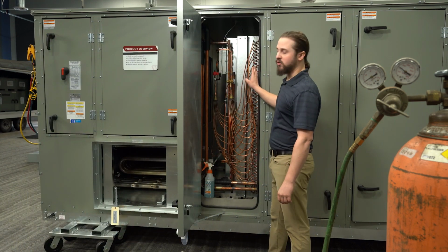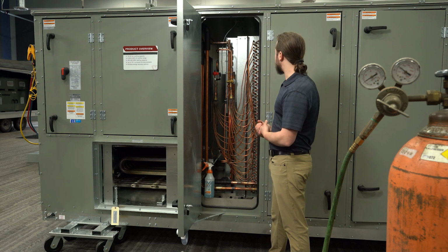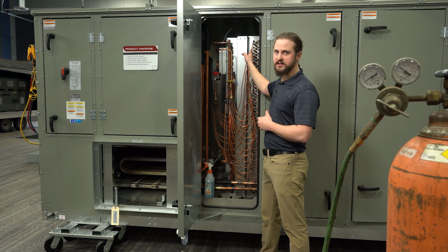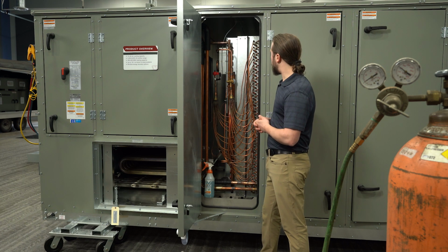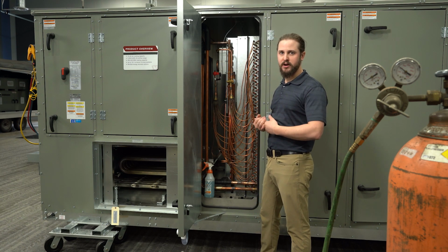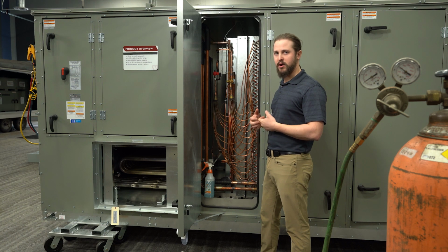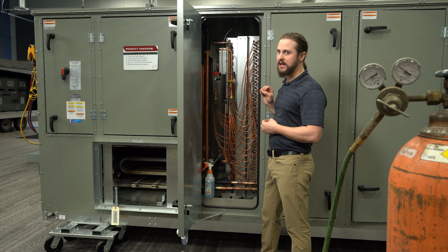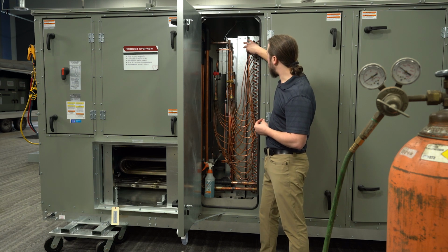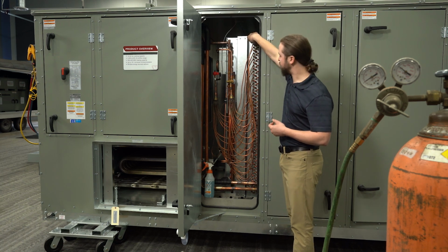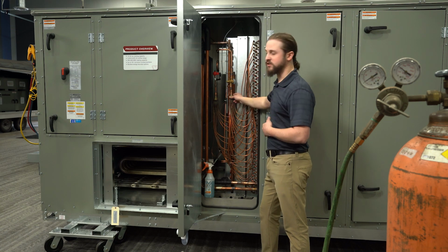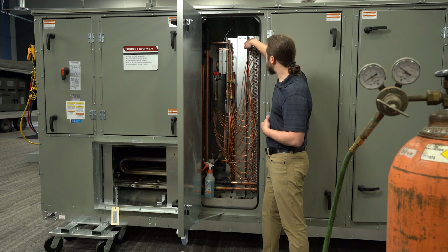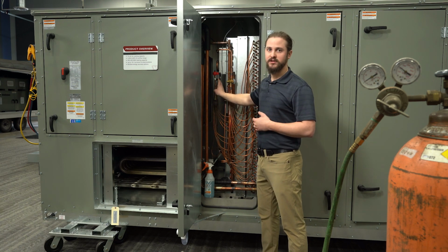Okay, evaporator or cold coil section. The reason I brought you over here is to look at the circuit A and circuit B coil interlacing. What I referenced before was removing refrigerant out of both circuits prior to just fixing or brazing a leak on one circuit. Reason that is, if you follow these distributor lines, we'll use this top one for an example. We follow it down and it connects to circuit B. The distributor line directly below that, if you follow that, that actually goes over here to circuit A.